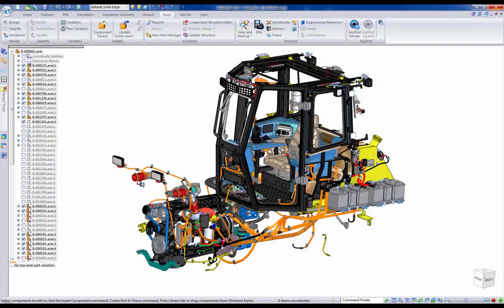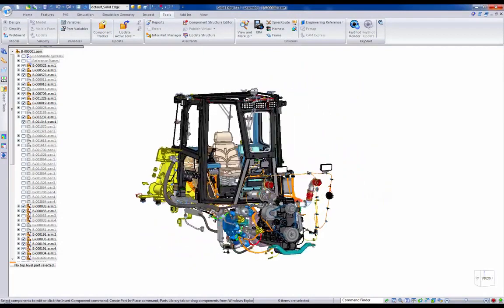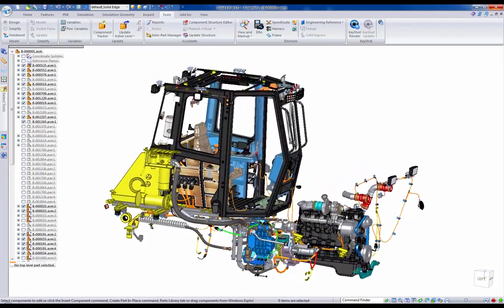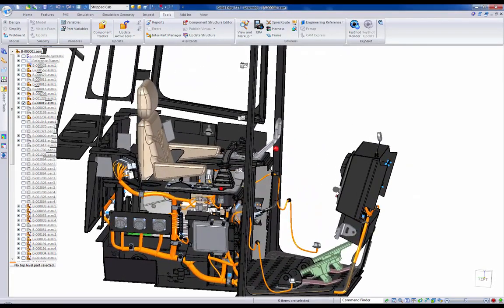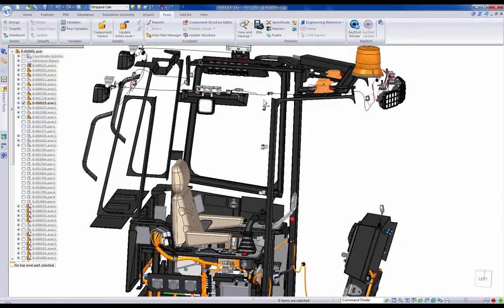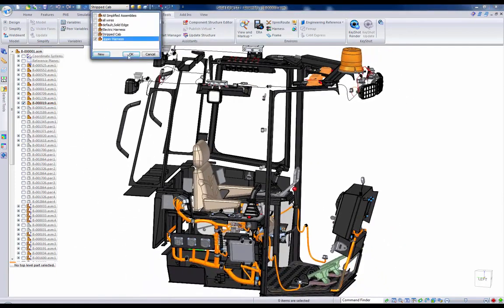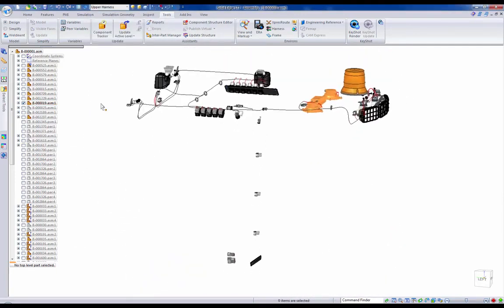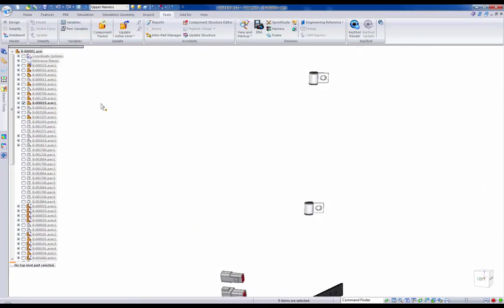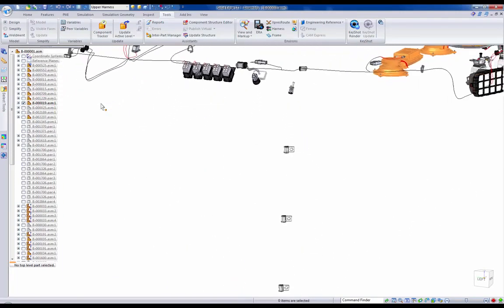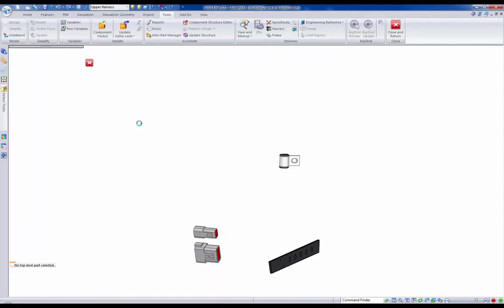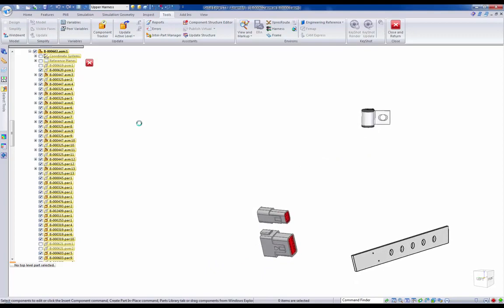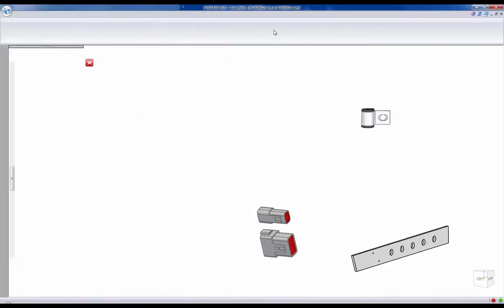As you can see, we already have the majority of the harnessing done on our cab assembly, but now we need to include our new harness into our Solid Edge model. When routing wires, cables, or paths, turning off background components using display configurations is a great way to easily locate parts for use in proper placement. Whether creating wires, cables, and bundles from scratch or from an imported E3 schematic, Solid Edge's Express Route tool provides an easy user experience with consistent command options and prompts to walk you through the workflow, step by step.